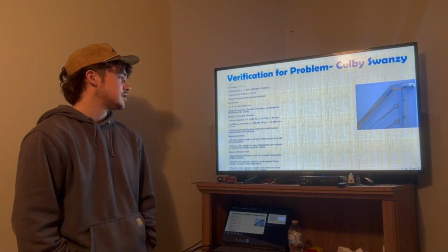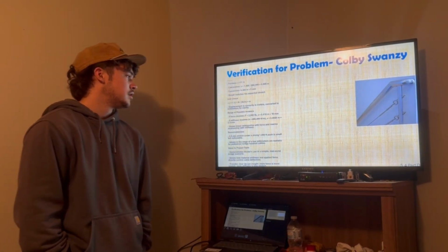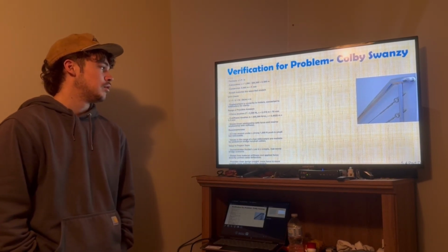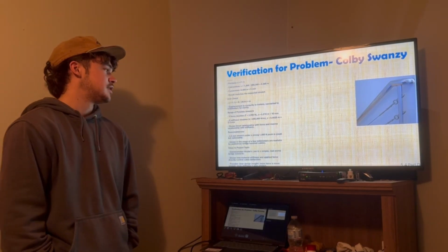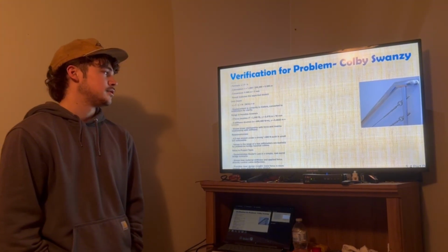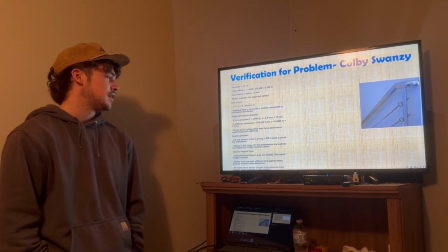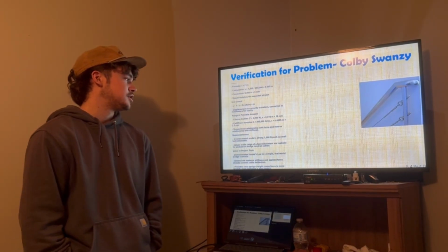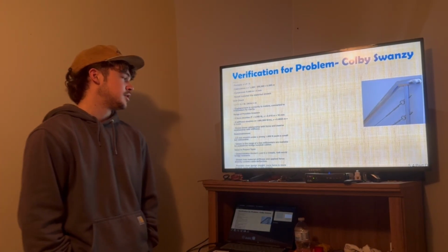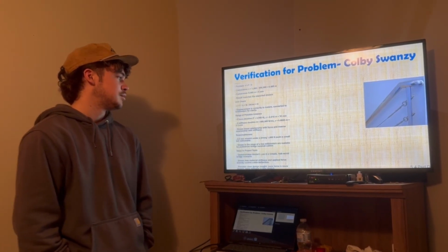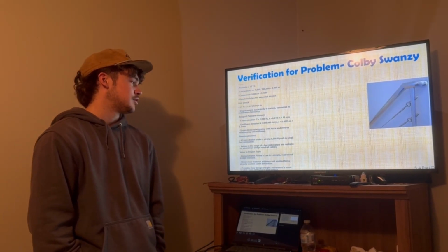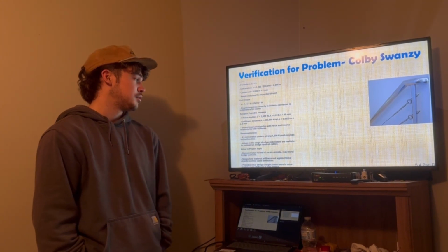Range of possible answers. If force doubles, F equals 2,000 N, then X equals 0.010 m equals 10 millimeters. If stiffness doubles, K equals 400,000 N/m, X equals 0.0025 m, which is 2.5 millimeters. It shows a linear relationship with force and an inverse relationship with stiffness. Reasonableness: a 5 millimeter stretch under a strong 1,000 N push is small but noticeable. Values in the range of a few millimeters are realistic for pedestrian bridge handrail cables.